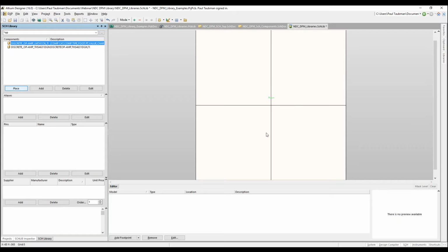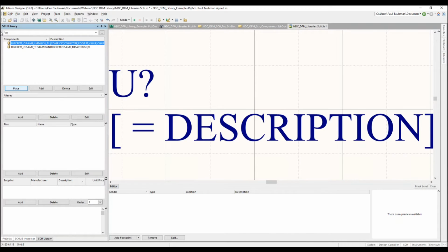In Altium Designer, when you are creating, whether it's a symbol or even a footprint, you've got to build it around the origin because it needs to know where to put the cursor in relative reference to where you're working. I'm going to hit another two hot keys, VF, and by the way, VF and VD are just these little underlines that you see here. So the letter V is actually the View menu.